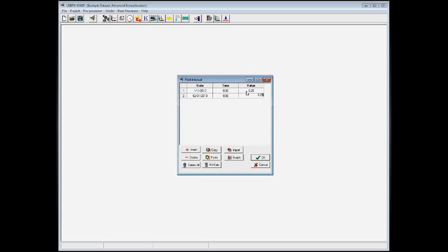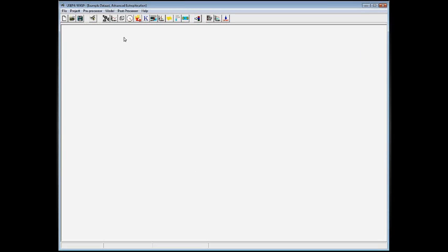That means that as WASP is going through time, it'll use whatever the interpolated values are between the current time and the next time as the printable. So in this case, it's constant, 0.25 days. Okay, once we have the printable in there, we're going to leave this screen and continue on to the left. And the next one is the segment screen.